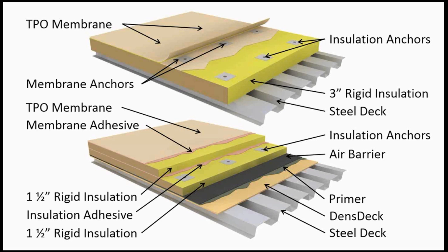Well, we had talked about doing this because they were having to phase in a very small area. One of the reasons for putting dense deck down in a system like this is because of construction traffic. But when you're doing a phased area where there's very few people working on it, we actually looked into and did some study on just doing the membrane directly applied to the flutes.